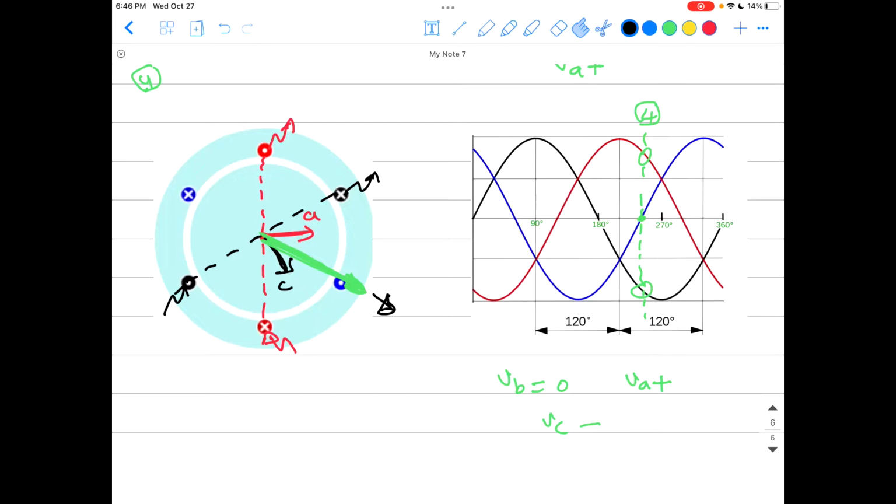But if you combine them together, so if you put those three-phase windings on the same core and separate them by 120 degrees, making a balanced three-phase winding, and rather than having just different three-phase voltage supplies, you have a balanced three-phase supply. That means the same voltage magnitude and a 120 degrees phase difference between the voltages applied to the three-phase winding. The resultant magnetic field will be rotating. That means it will have the same magnitude but keep rotating around the circumference of the machine.